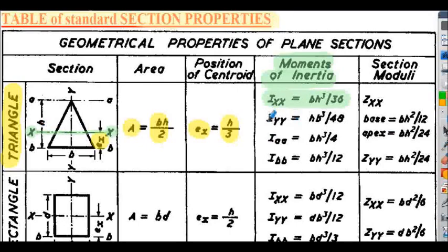They've stated the second area moment about the IY axis, that's this vertical axis. And they've also now stated the second moment of area about axis AA, the top of the triangle, and about axis BB, at the base of the triangle. So for different design considerations, we may need to find the I about these various axes, and this standard reference source shows how engineers would actually calculate these specific values. They wouldn't necessarily work from first principles using integration.